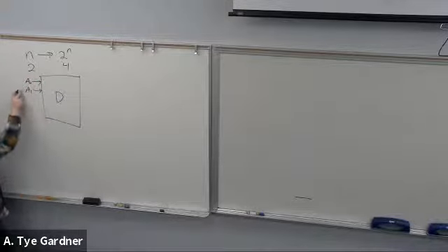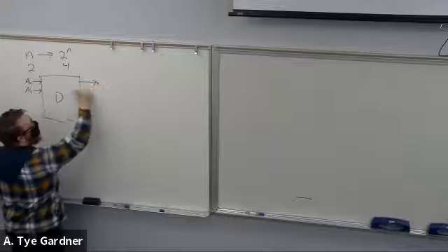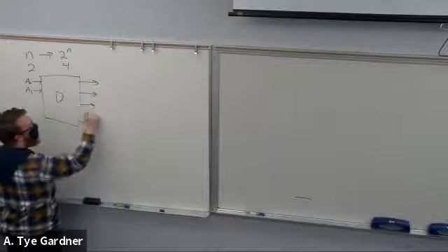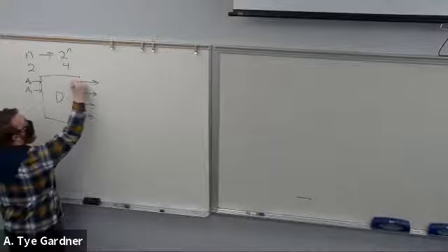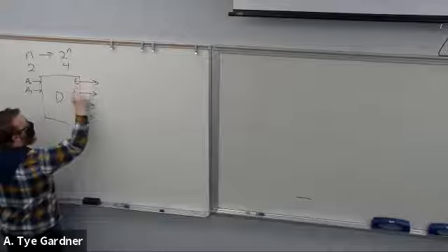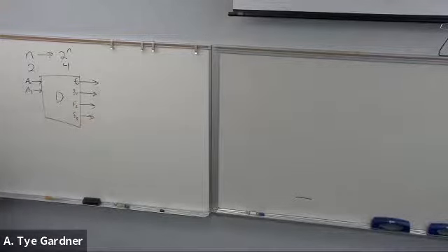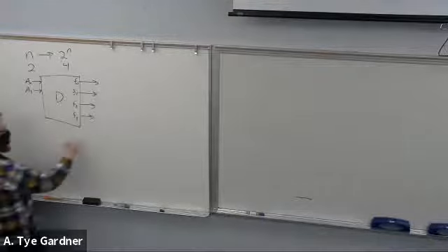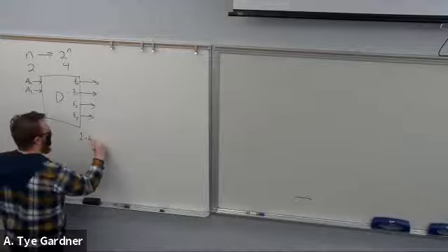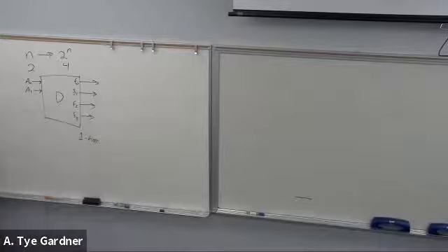So we're going to take 2 bits, A0, A1, and output F0, F1, F2, F3. Potential 4 bits of output. Now, strictly speaking, a decoder must be what we call one hot. What that means is one wire, exactly one wire, no more, no less, is on, based on the binary inputs.